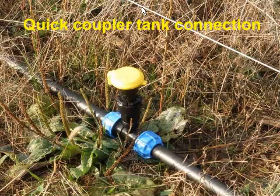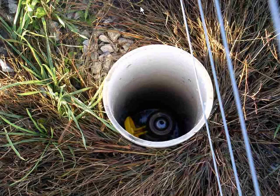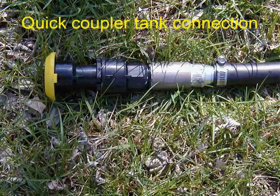Let's talk a little bit about couplers. Here's an example of a quick coupler that you would find on an HDPE pipe. If you have a buried pipe, you can have something like this where you've got a PVC going into the ground, so you have access to your coupler. Here's another quick coupler connection. This is at an end point or maybe an off spur, off a teed off point. Here's where you actually access the quick coupler in. That's what it looks like.